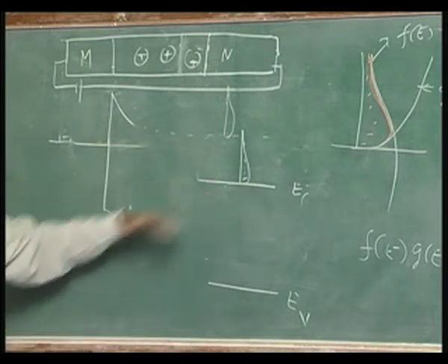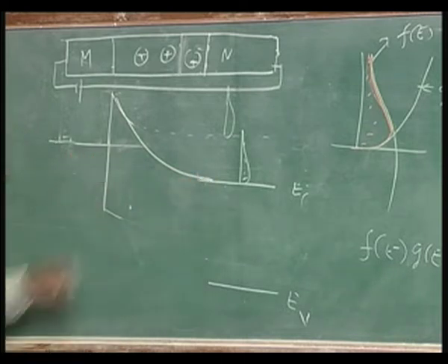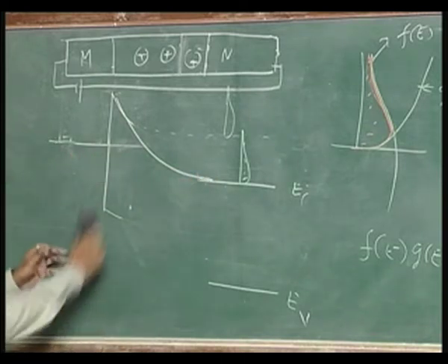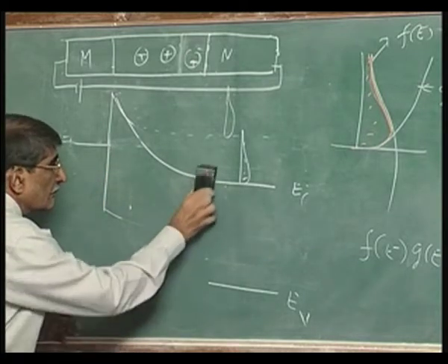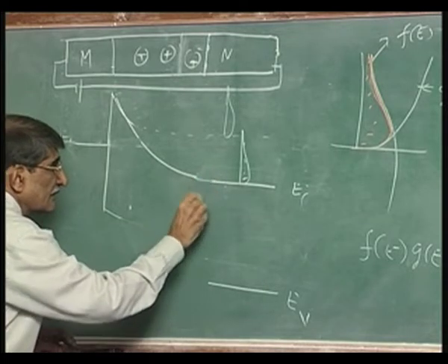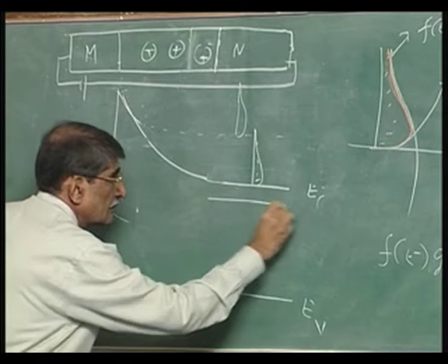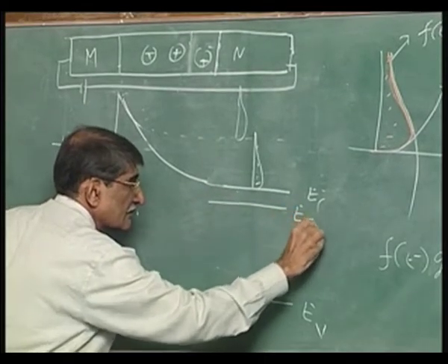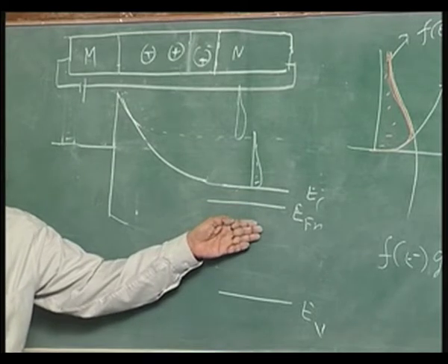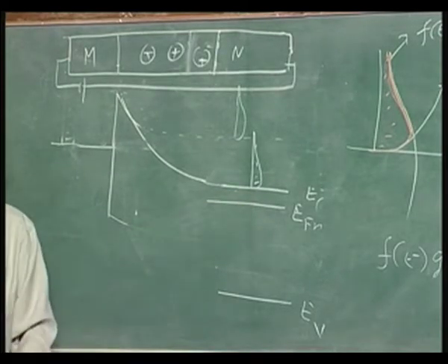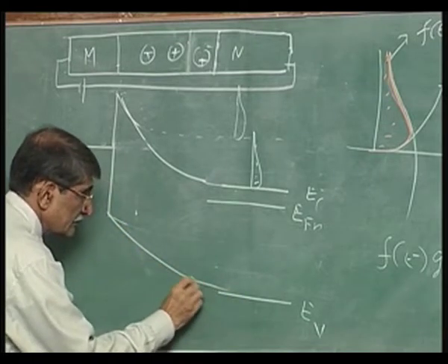The whole level has come down. And you can't draw the Fermi level here; you draw it only there and call it the quasi Fermi level. It means you can still compute the electron density using this Fermi level with respect to the conduction band. That is the meaning of quasi. You do not talk about that here. And from here, the whole thing comes down.